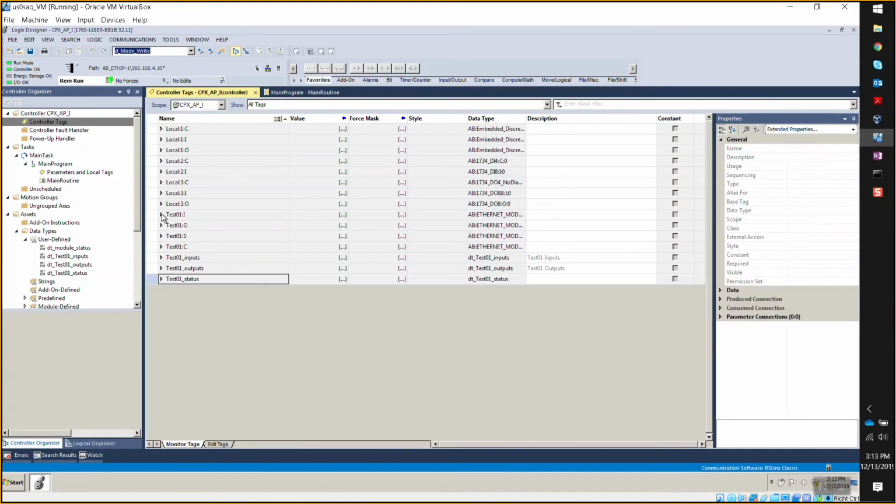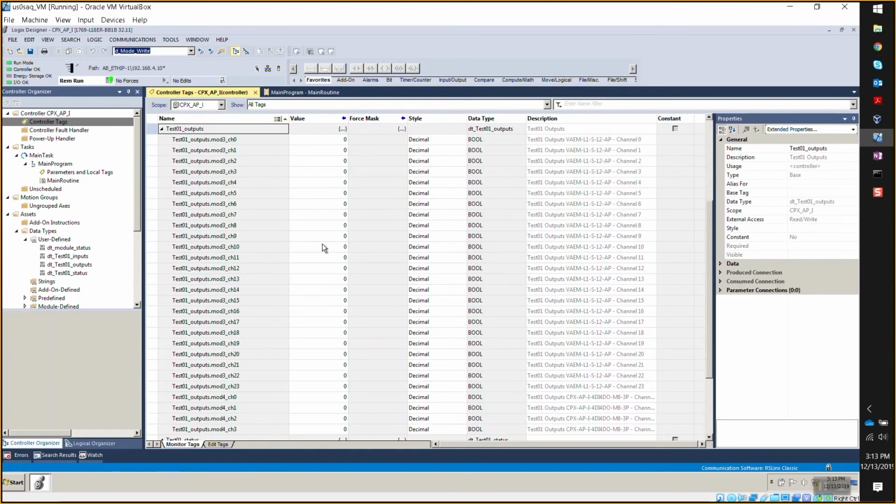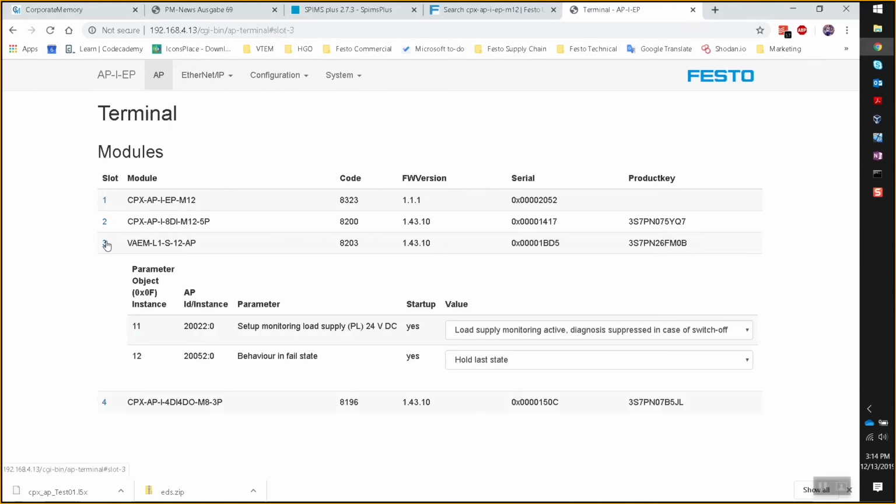So yeah, I think that from here I can keep working on my project. One final thing here now. If you remove the Ethernet IP cable, your outputs should stay on. Right. Okay. Yeah, because we changed that parameter, right? We changed that parameter from default of reset to hold last state. Yeah, we did that here and then here. Correct. Hold last state. Okay.